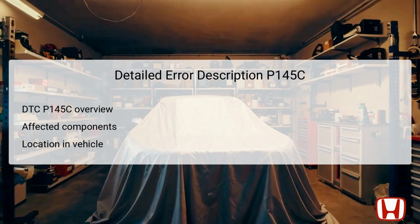The primary affected component is the EVAP canister purge valve, which plays a critical role in regulating the flow of fuel vapors from the EVAP canister to the engine intake. Located typically within the engine bay, this valve is electrically operated and only opens under specific conditions, allowing vapors to be combusted during engine operation. An effective purge flow is crucial for maintaining low emissions during vehicle operation.